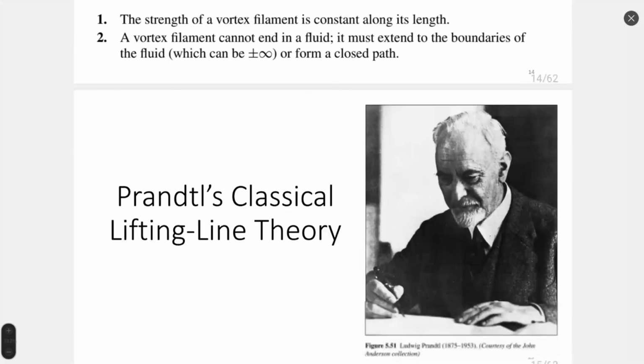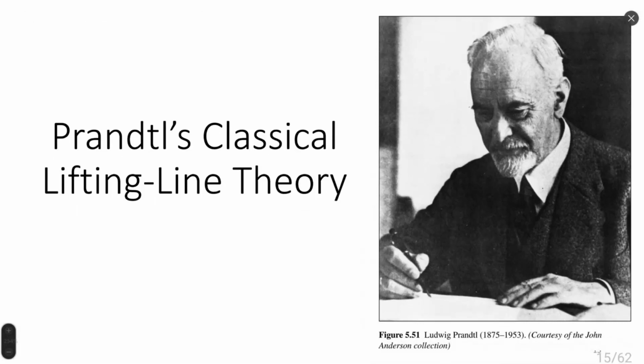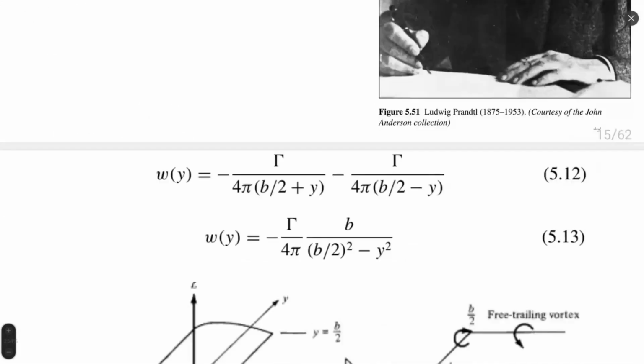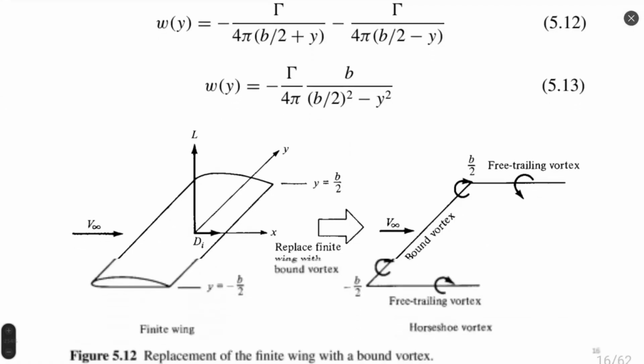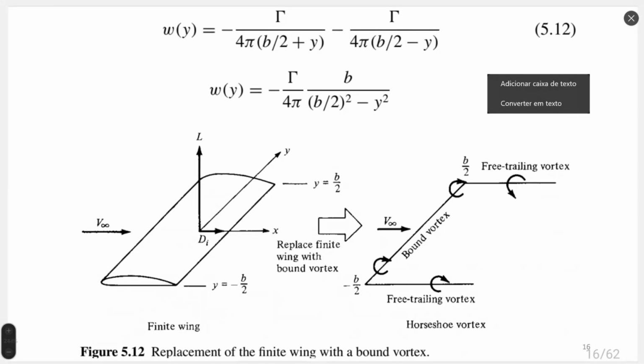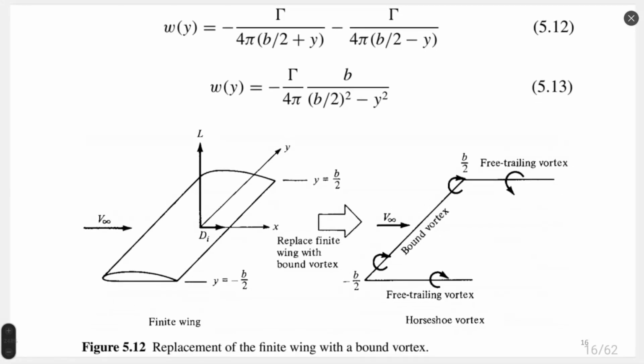Okay, Prandtl, very nice picture. Historical thought. Prandtl's lifting line theory is the following. Prandtl suggested that the downwash velocity, or velocity representing losses on the trailing vortex, would be calculated in the following way, as you see in equation 12.